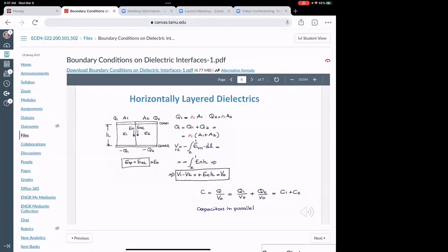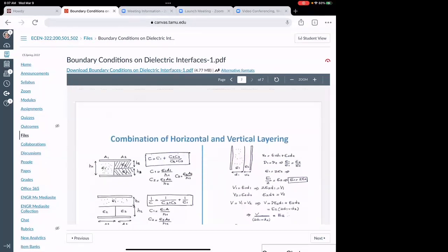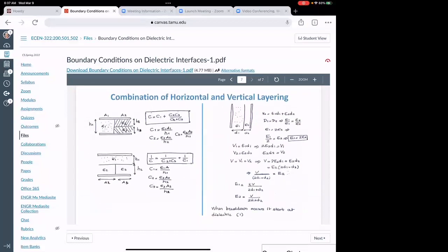In that case, it's like you have 2 capacitors in parallel. So the equivalent is, as you can see here, as if you have 1 capacitor here, this part, in parallel with this capacitor. And that makes your total capacitance C1 plus C2. So what I have as another example, here is even crazier. What do you do in this case on the basis of the previous one? Practically, you have 1 capacitor in parallel with a series combination. You don't even have to solve it. What would you have here? 1 capacitor in series, excuse me, with a parallel combination.